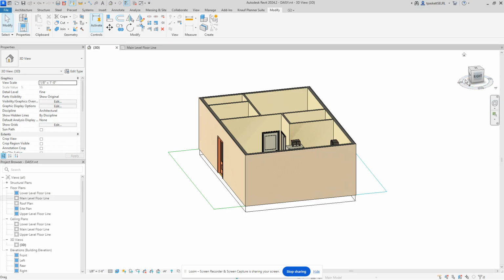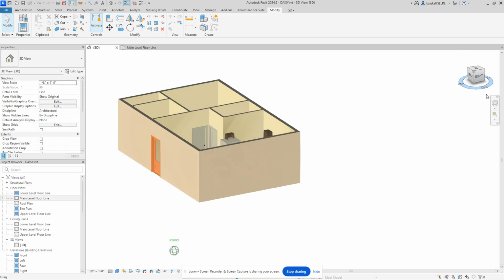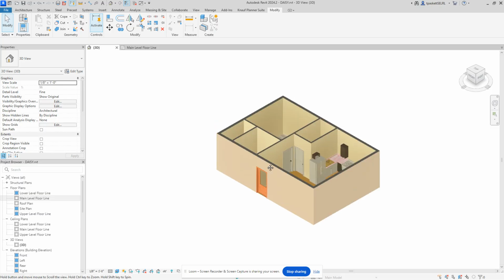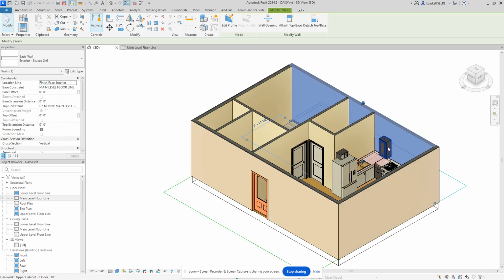And now we're going to get ready to paint. Now, there's a couple of things about your house that we need to talk about before we do that. Let me go back to home view. When we drew this, the back wall covers 3 rooms: a bedroom, a bathroom, and a kitchen. We're probably not going to do them all the same color unless we're doing track housing and it's all white. So I'm going to need to break this wall up, but I don't want to cut the wall apart because for the contractor, this wall tells all about how many studs they need, how much plywood, how much drywall. All that information is built into that wall. So I don't want to cut it if I don't have to.